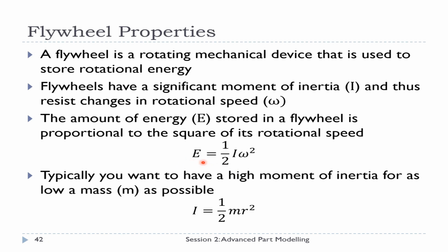So if you would like to increase the energy stored in the flywheel, we should increase the moment of inertia in this equation. So how can we increase the moment of inertia? It's basically adding mass to your geometry at a greater radius from the axis of rotation. We will look at how we can use these parameters in SolidWorks.